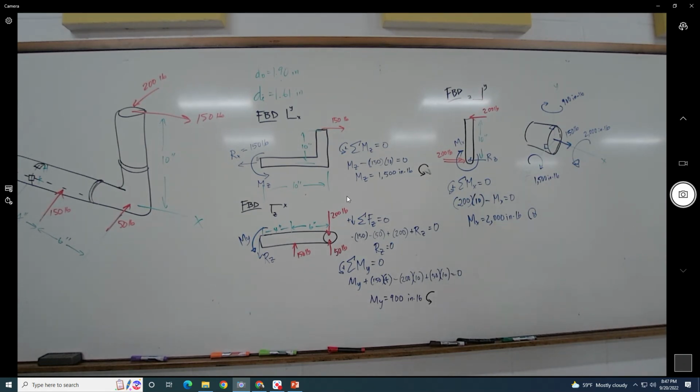But the real thing that we want, maybe we want a stress element out of this. We want to pick one of the stress elements, and we start going down the list. First off, notice, what about transverse shear? There's none, yeah, right? Because we really need to be in the Y direction or the Z direction to get anything out of it. And then, all right, so axial stress? Yep. Sure. So we're going to get F, that would be the Fx over A.